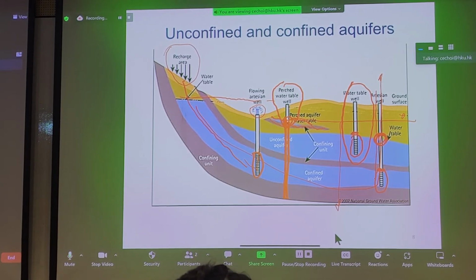in that you can only measure what you get at the tip of the piezometer, right? So in these cases, it would be useful to have a standpipe in combination with piezometer, so you can have a much more in-depth interpretation of how underlying hydrogeology is affecting your decisions as a geotechnical engineer. So that's all I want to talk about the limitations of installing piezometers at the wrong height.